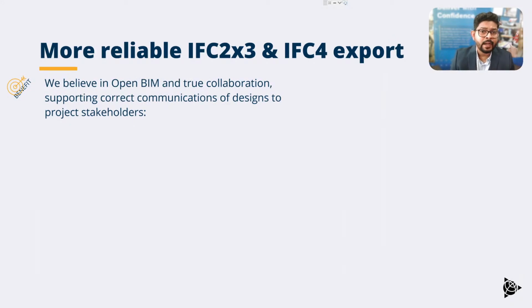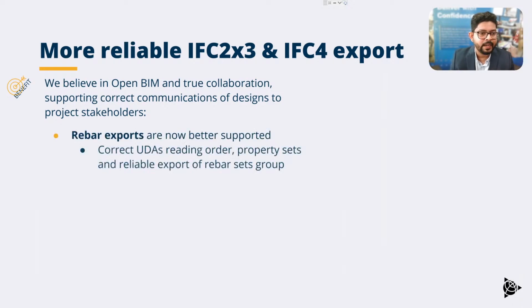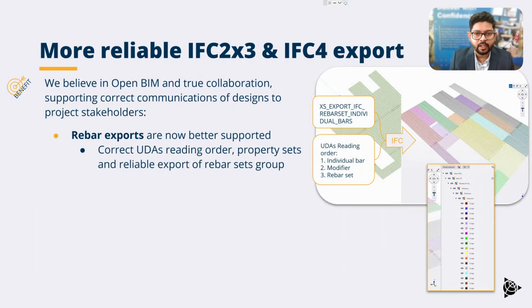And now if you look at the IFC export, that is IFC 2x3 and IFC 4 export, the Rebar workflow has been enhanced. Specifically for the Rebar set export, it reads the user-defined attributes in the correct order. That is from the individual Rebar to Rebar set modifiers and then Rebar sets.